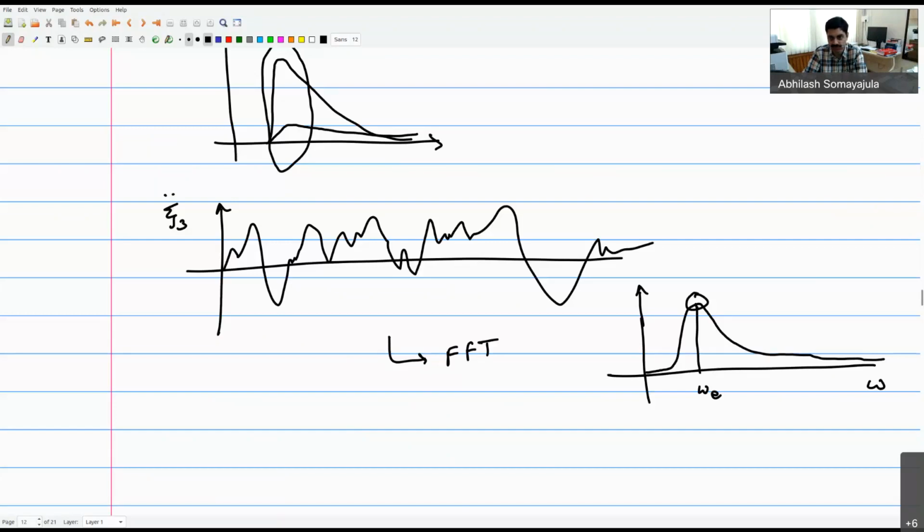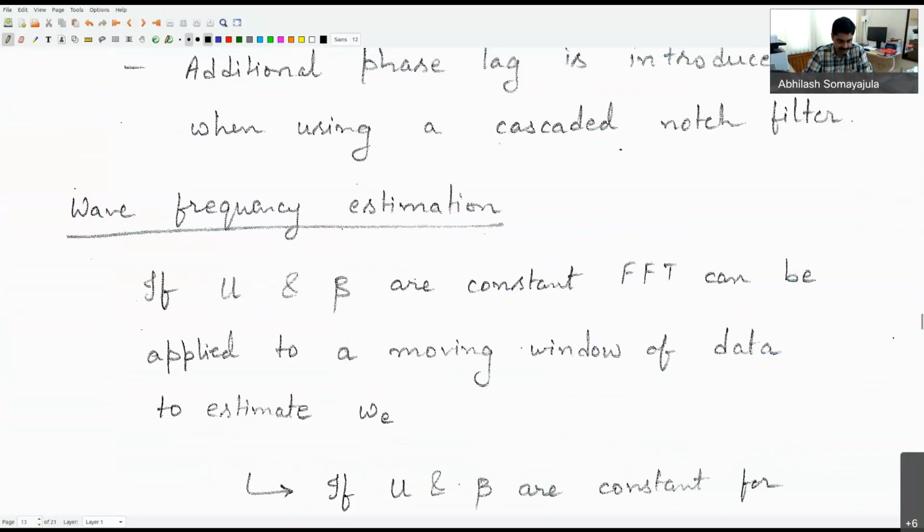Okay, everybody with me so far? So that once I do that elimination, whatever is the output left, that can now be given as a feedback to my control system, which can then try to compensate for those disturbances which are coming in. Okay, so this is the basic idea which you will see for a long time. Mostly this is how it was implemented back in the day. Okay, low pass filters, cascading notch filters and other things were what were used.